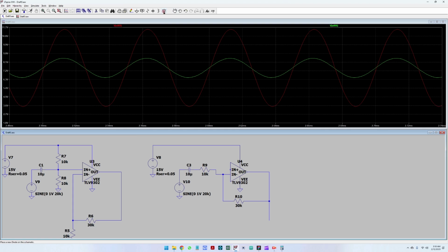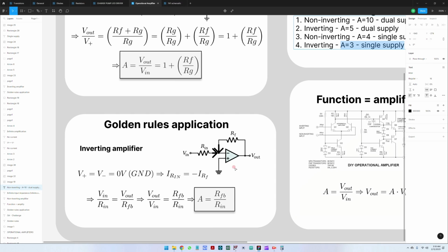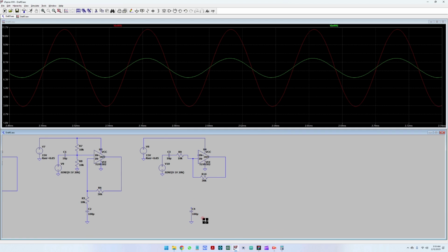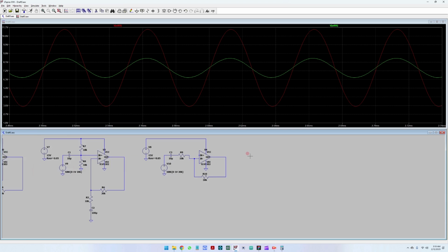Great. So going back to our previous design, we can see here that this is connected to ground, or the half level of what we have supplied. Now what we have to do is create this ground layer here. So let us go back to LTspice, and here we have to create this ground level, which we have to connect to the non-inverting input.